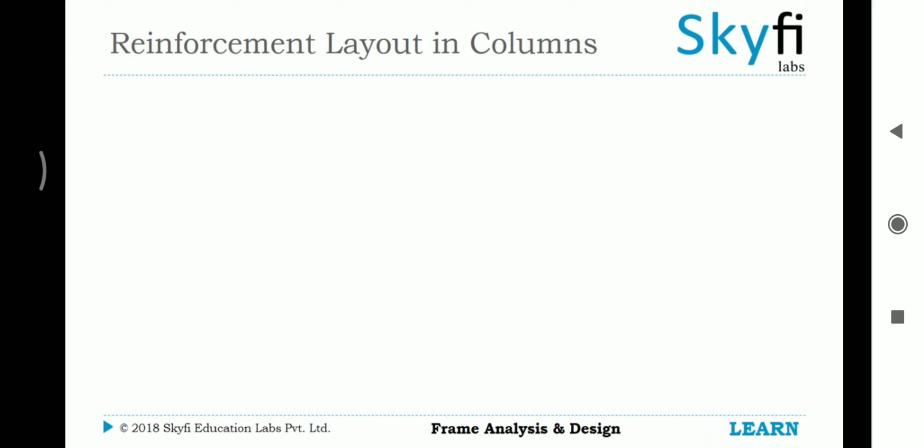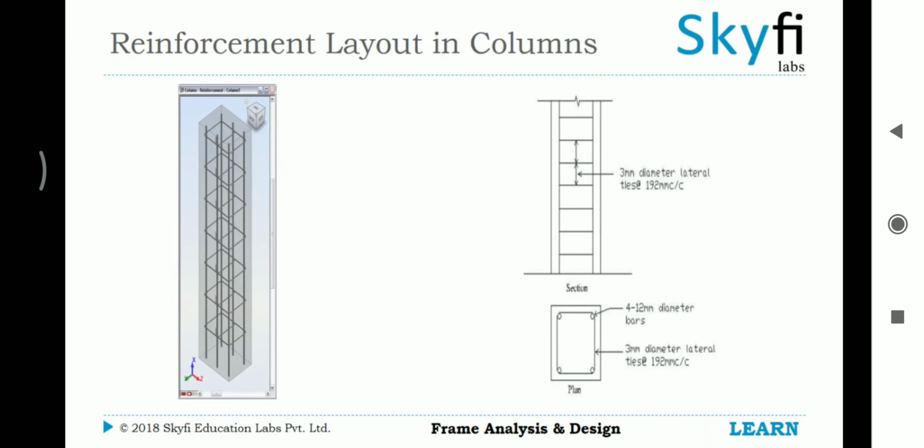To undertake the compressive loads, concrete columns, like beams, are embedded with a steel frame to provide reinforcement. The reinforcement provided along the length of the column is the longitudinal reinforcement, which resists the axial forces and the bending moments that the column is subjected to.